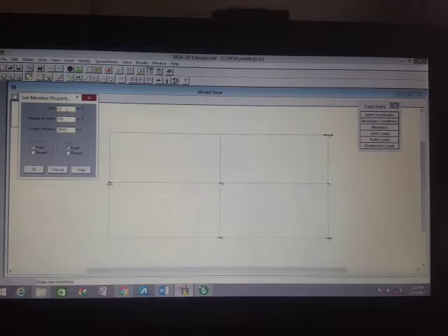So it says on page 12 that our value of I, our moment of inertia, is 500. The area of member AB is 15, so let's input 15 inches squared. And then the moment of inertia is 500. But take note that in the problem, the member from A to B is 2I. So meaning that we have 1000 inches to the fourth. Okay, and then the Young's modulus is 29,000 ksi.